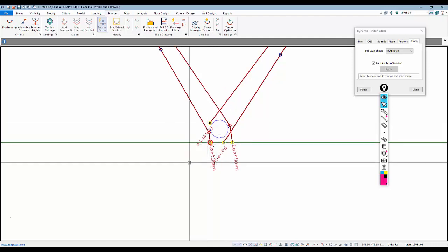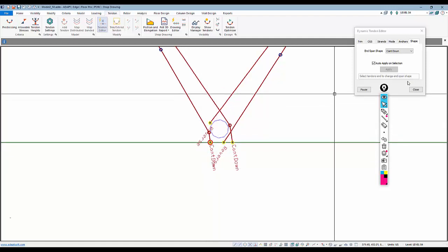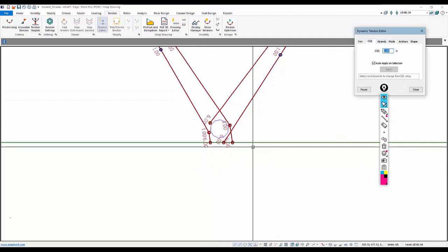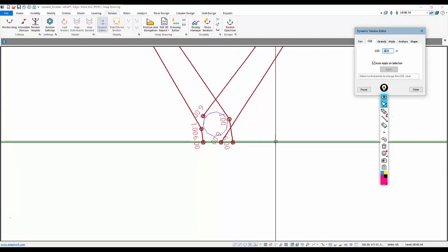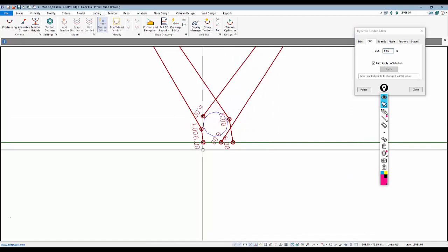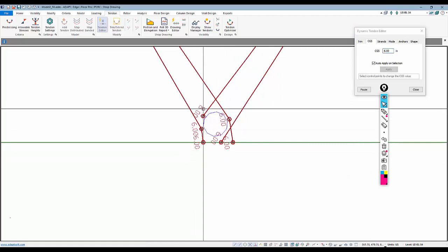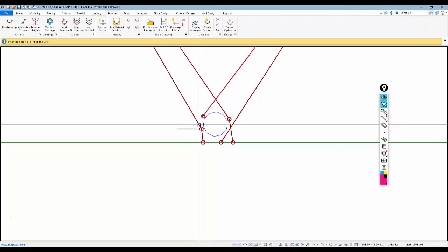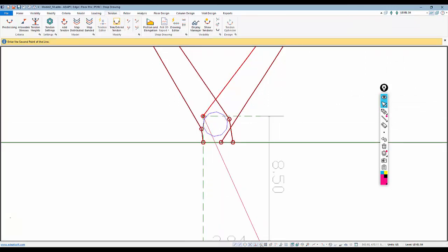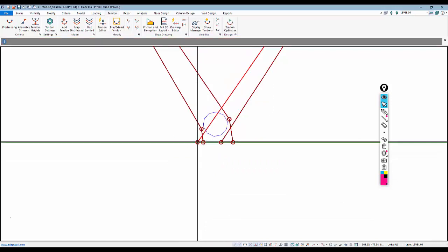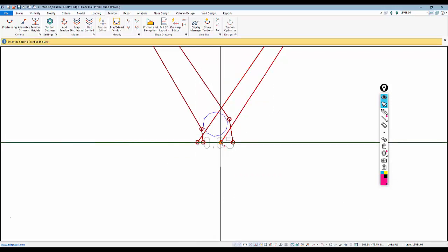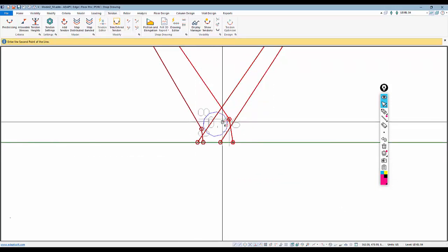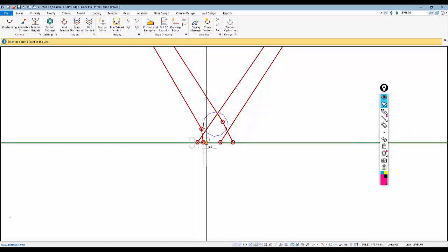I'll change that one to cantilever down. And then if I go over here to CGS, we're going to drop the CG to 6 on those. So that will become 6 there and there. And then this one, we're going to drag these out to the edge of slab, something like that. We can just straighten these out.